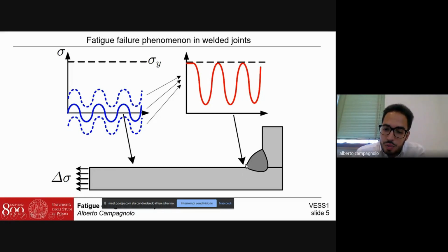When we observe close to the weld side locally, we see that the stress range is scaled up. This is due to the fact that the weldment introduces a notch effect. Indeed, the stress flow is perturbed by this geometrical variation of the structure, and therefore flows through the attachment, and not only on the base plate.